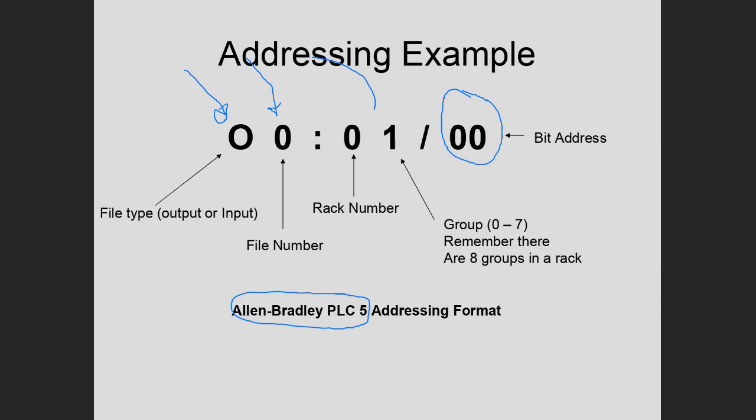So once you know what row or what rack we're dealing with, then you figure out which screw terminal am I connected to, and that's the actual bit address. Remember, they count with 0: 0, 1, 2. If I was connected to maybe terminal 2, the third one from the beginning, starting with 0, 1, terminal 2, then this bit address here would say 0, 2.